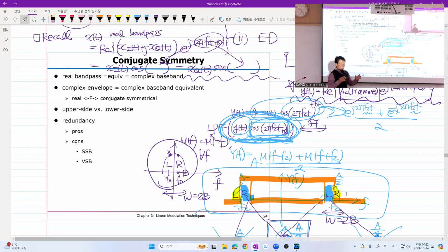Then, what would be the next step as an engineer? Probably you will think about having a new modulation scheme that is twice as spectrally efficient as DSB. And you may say that, okay, twice, that's not a big deal. I can eat one set of McDonald's or 2 sets of McDonald's. What's the problem? As I told you, this frequency band is very, very expensive.